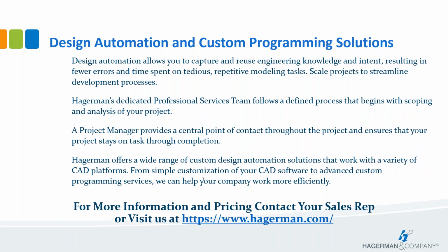But a lot of people do that with the layout tabs. They have to be using vanilla AutoCAD, because the tool sets will not allow you to do that, since they're designed to be one drawing title block per drawing DWG file. So you can't do that in AutoCAD Electrical or Plant 3D or Mechanical and so on. In vanilla AutoCAD you could, it just would require a little bit more creative programming to get it to work. But there's no reason I couldn't do it. I've done similar type stuff.